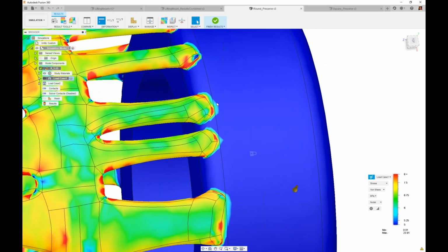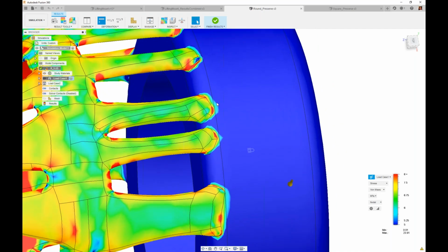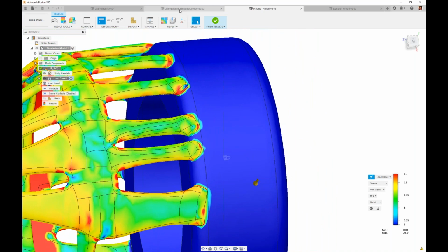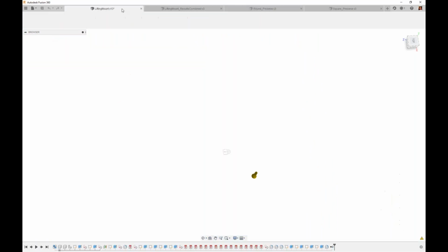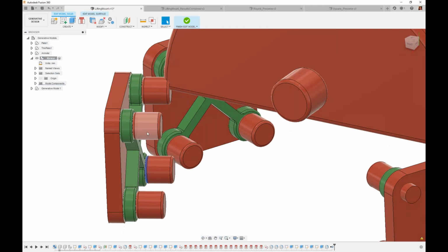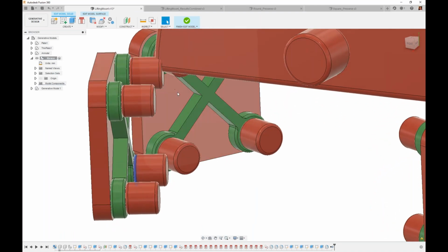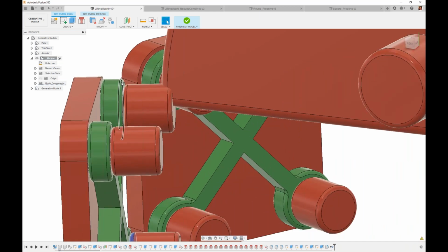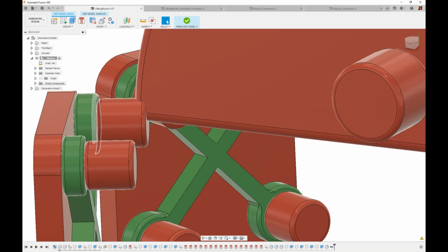So from a recommendation standpoint, depending on how your geometry comes in, if you think about where your obstacles are and how some of that geometry may have to wrap around and attach to that preserve, having a fillet gives it a different landing area.